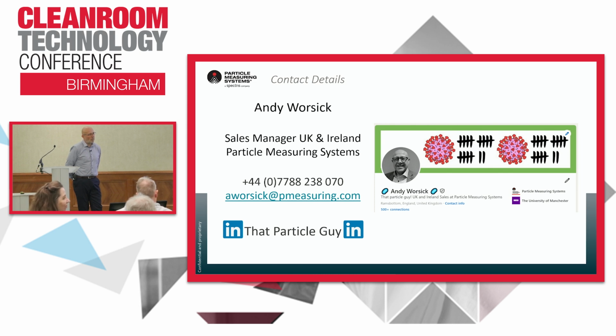Because remember, we're using particles here. The semiconductor industry is actually worried about killer particles that land on the device and cause failure of a circuit on a chip. We are not interested in submicron particles at all. There's no specification for submicron particles in parenteral products. We're using it as a surrogate. We're sampling particles 0.5 and larger and 5 and greater, because it gives us an immediate indication of a contamination event.